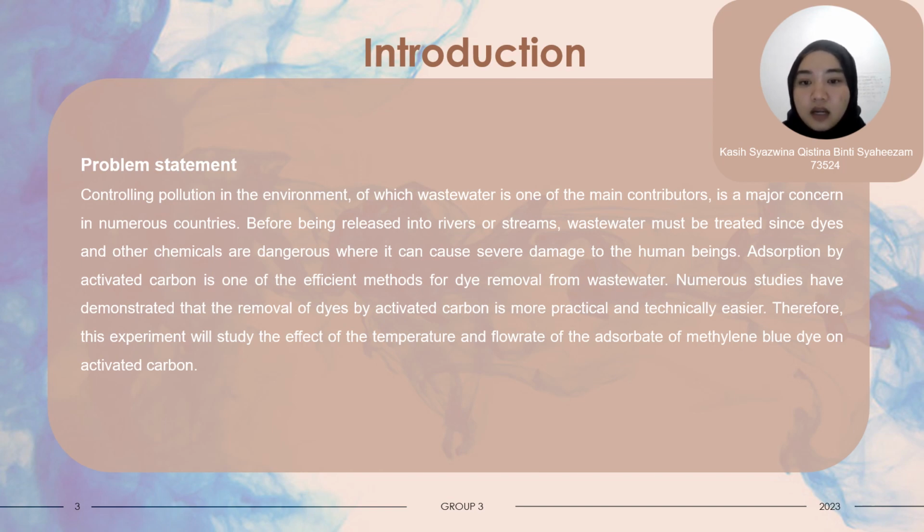Adsorption by activated carbon is one of the efficient methods for dye removal from wastewater, as it is more practical and technically easier. Therefore, this experiment will study the effect of temperature and also the flow rate of the adsorbate of methylene blue dye on activated carbon.